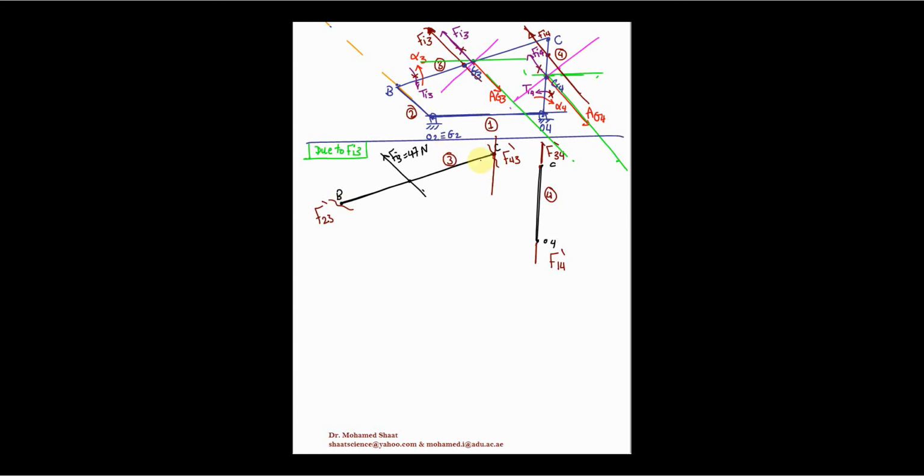But before that, when this one was unknown, we could not do any force analysis on the link unless we specified the direction of this force first. How did we specify the direction of this force? We got it from link 4. Link 4 is a two-force member, and from this condition we understood that this force should be along the line that connects these 2 points together, and definitely this force should be parallel to this one, so we got the direction of F43 dash. Now we can do force analysis for this mechanism.